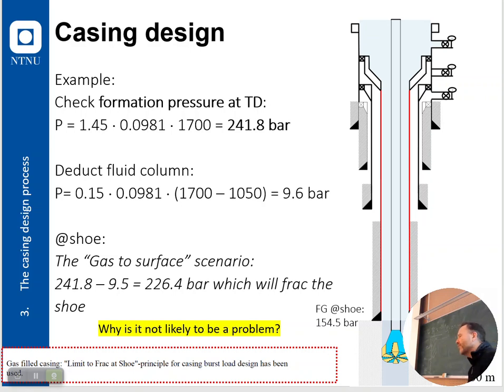Something that was very different when I started drilling outside of Norway was that formations are so tight that you can kill a well with water, or just brine that is a little bit heavy.